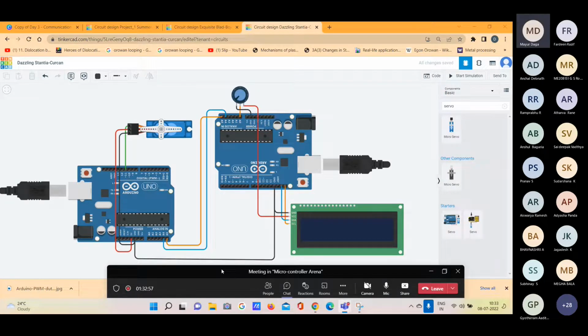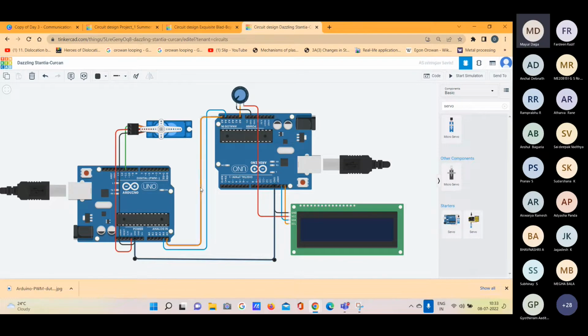If we have to show that the SDA line is going high to low while the SCL line is high, and the SCL line going low to high, they are relative, right? So that must be common for both. The grounds of both are connected so that the ground is common to the I2C bus, and it is the base for the clock signal and base value. Base value means the low voltage value. I hope it is clear.